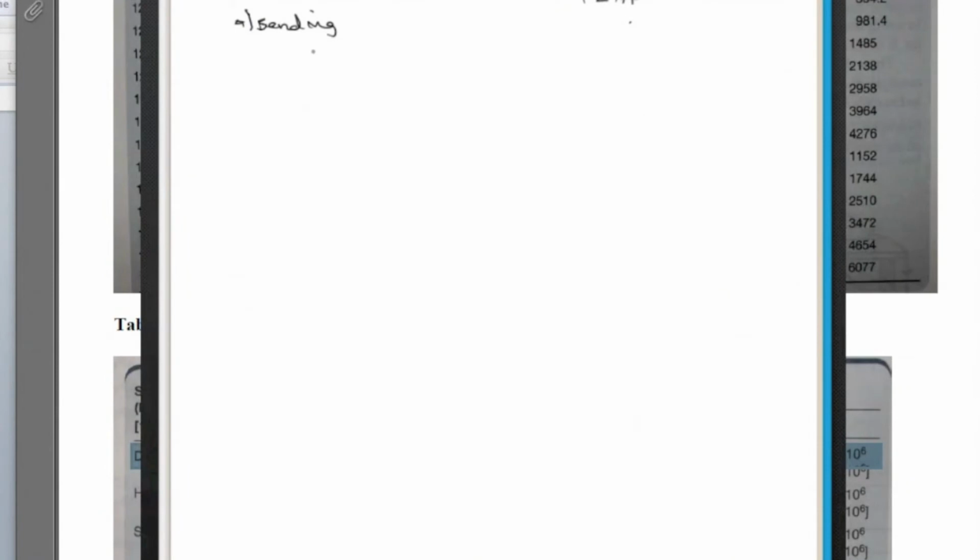Okay, so bending, we're going to use the equation here. L equals 10.95 times the square root of FB S over W. And FB from that chart with the Douglas fir larch is 1450.